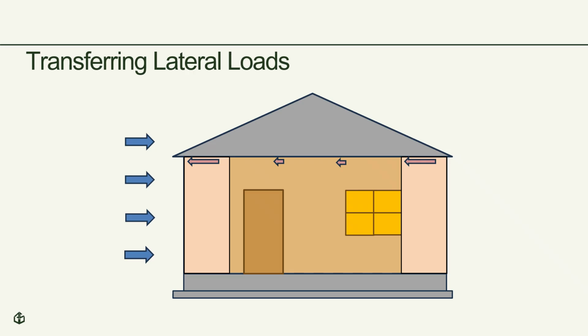The brace wall panels then need to be able to resist overturn. As you can see, the load within the panel as it resists the overturning forces means there is a point load acting downward on the right side of the panels, and an uplift load on the left side of the panels. As we look at the code provisions for wall bracing in other parts of this series, this will help us better understand the code provisions. You can also see that ultimately all the loads, like gravity loads, are transferred to the ground.